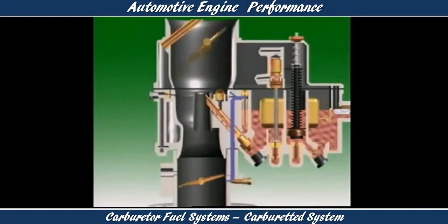Closing the choke valve closes the carburetor intake. The pumping action of the pistons creates a low pressure area below the valve even without venturi action. This low pressure causes fuel to flow from the discharge nozzle and from the idle and low speed ports and provides the rich mixture needed to start the cold engine.